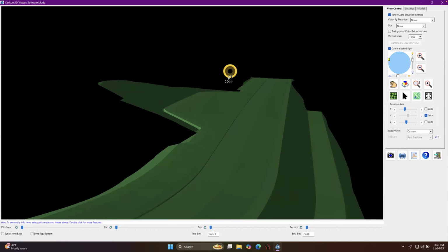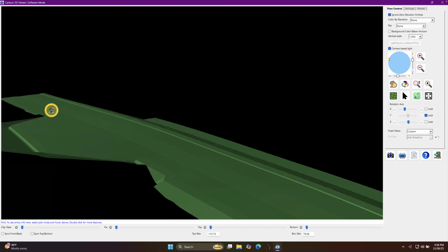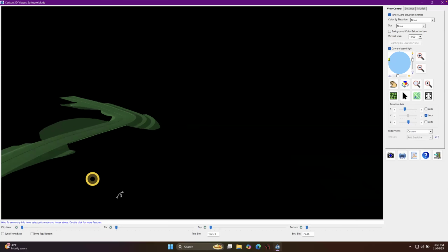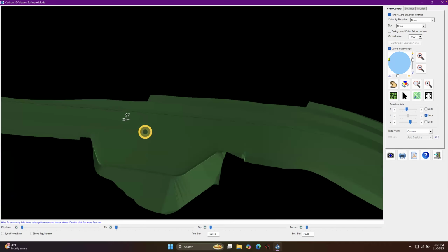Maybe you're along a street in the center line and you're putting in tree boxes. So your sidewalks are going to follow the road and then it's going to make a little circular path around the tree boxes, so you can use that technique to do that kind of adjustment without having to make these separate templates that show this widened area and then do a template transition. You just do it with those template point, centerline template point profiles.